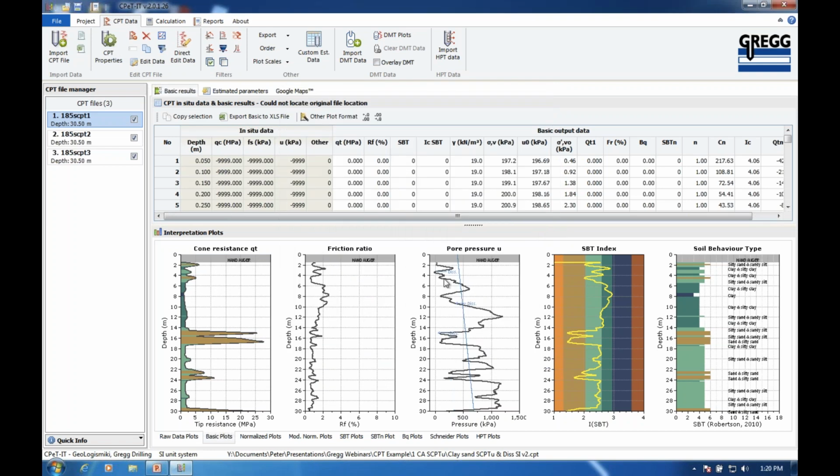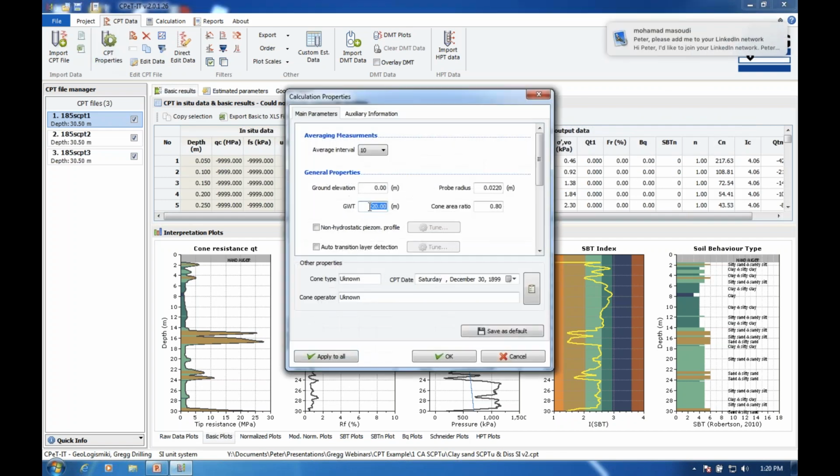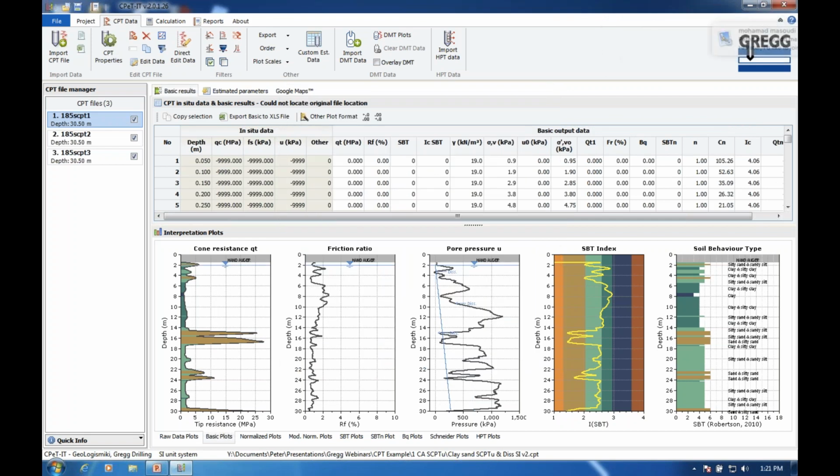And the way to check if you've got it right is you again go to the ground surface and you check that the effective stress is being calculated at 0. So now you can see that the total stress is the weight of water and the pore pressure is the weight of water, because it's actually added the 2 on, so it's still getting an effective stress of 0 at the ground surface. So yes, you can put in a water table above. I'll go back to 2 meters down.